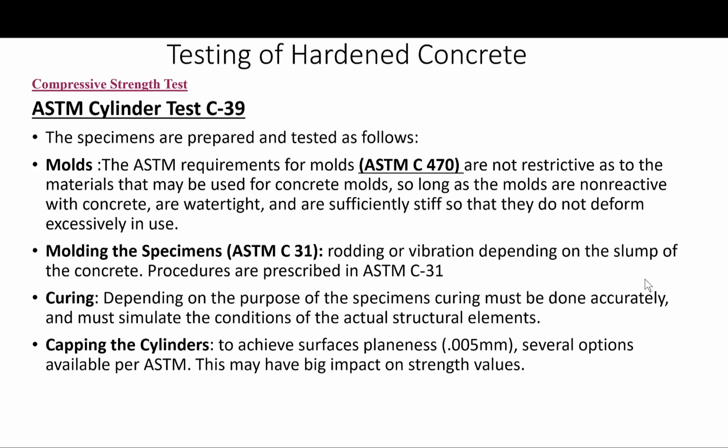So it is required that the specimen ends must be plane within 0.05 millimeter or 0.002 inch. One way to achieve planeness is by grinding the ends. This is satisfactory, but it is expensive and time consuming, and quite frankly, I will not guarantee the results 100%, depending on the operator who is doing the grinding.